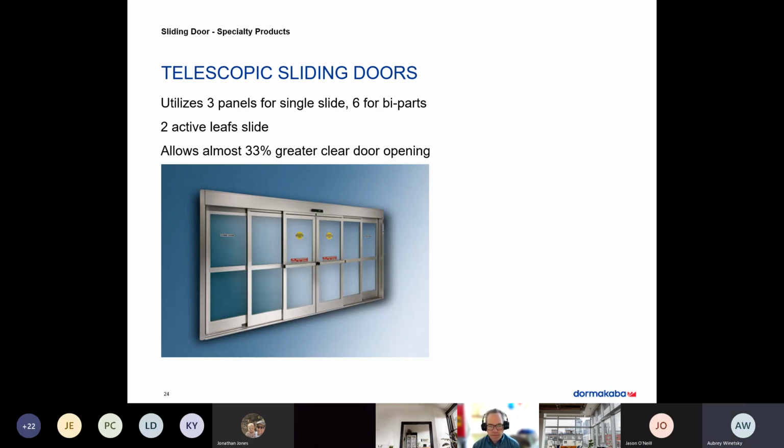Yes, correct. And really, because I work with our glass doors as well, I would say the only glass door that you really have to worry about deflection on is if you're using just patch fittings on a pivoting door. And if you're going really tall, something over 9, pushing to that 10-foot range, that's really where deflection is going to be an issue, especially if you stay with like 1/2-inch glass. And we follow GANA, which is the Glass Association of North America, and they have recommendations on what to do there. But it's really only patch fittings. As long as you have a bottom rail and a top rail, you're usually good to go with that.